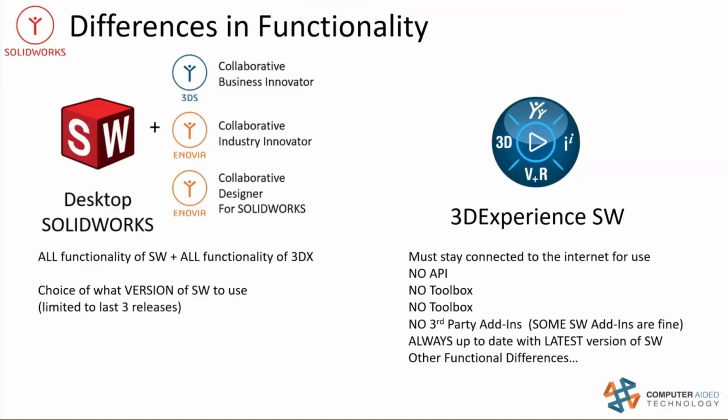Right, and this allows multiple users to be working on different parts of, let's say, the same assembly. If you're familiar with the PDM products, you can check out or reserve, take ownership of certain files. That allows that person to work and make changes to the file. They make an update, and you'll get a notification in your task pane as you're working in SOLIDWORKS that you may have a version that's not currently up to date. So you can refresh from the server, or you can just ignore that until you want to refresh all the parts that are being reworked, and then have all that refresh done at a certain time of the day.